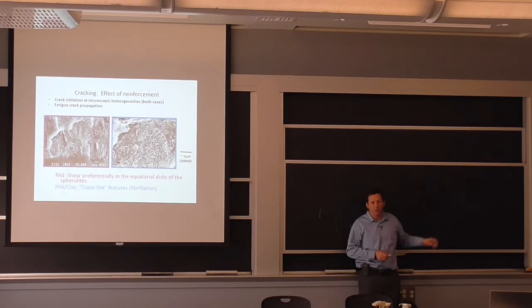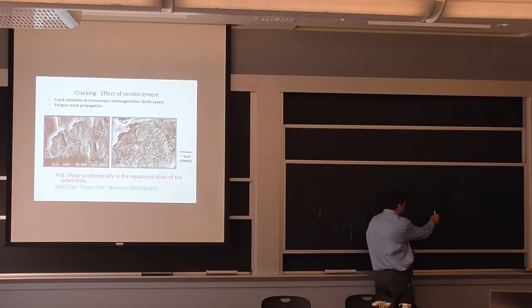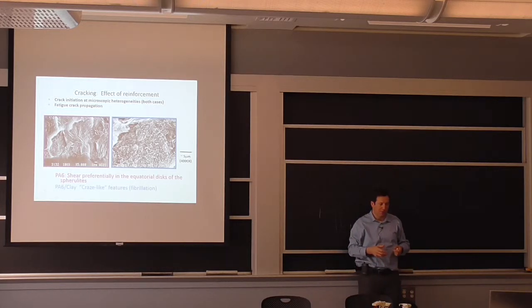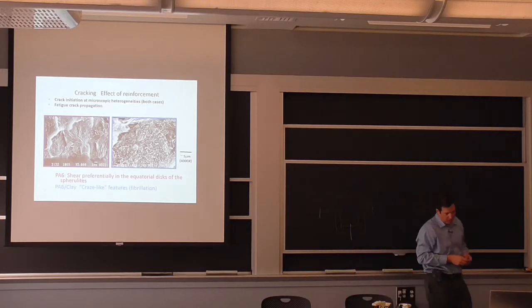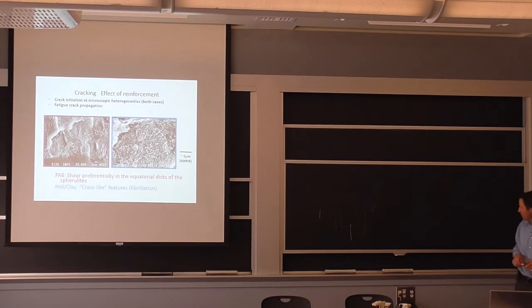So you have the melted polymer, and then you cool it down, it starts to crystallize, but here it's crystallizing from those surfaces, so instead of starting from a center, it's forming this more already kind of an oriented structure as opposed to the starting point. So this way of adding reinforcement actually changes also the crystallization of the nylon in this case. So it causes improvement.